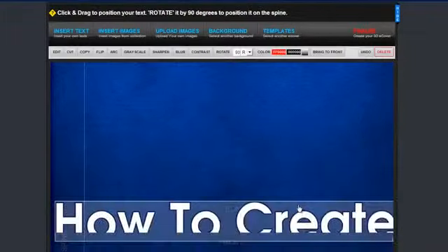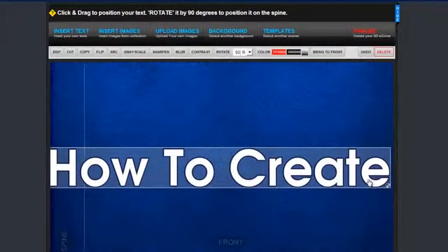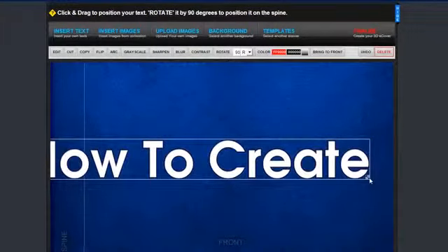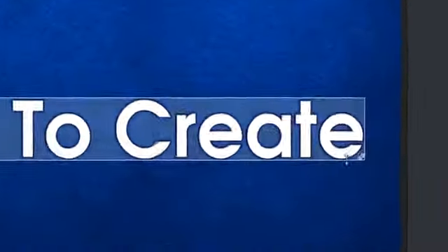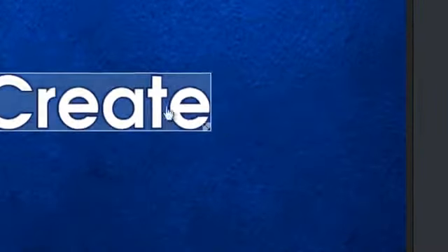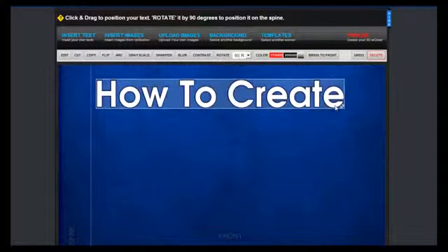After the text is added to the design, you can move it around to position it. Notice the text editor didn't have a font size option. That's because once added to the design, you can click on this bottom corner indicated by an animation arrow to resize the text. When resizing the text, you will notice that it constrained to its original proportion. In cases where you don't want this to happen and want to resize it to odd sizes, just hold Shift while resizing.